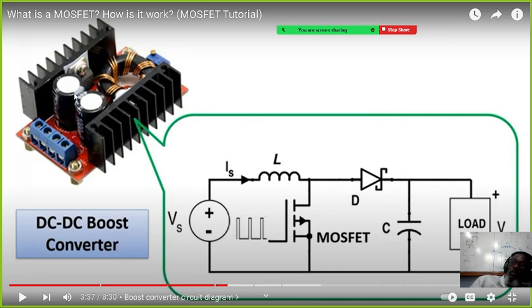Let's say, for instance, you have a rectified power supply, like the one that you made already. Then you can set up a boost converter on it by using a MOSFET and put in what is known as a trigger or a duty cycle voltage, a pulsating DC, and you can get much more current out of the power supply that you had built by using a MOSFET. Set it up like this.